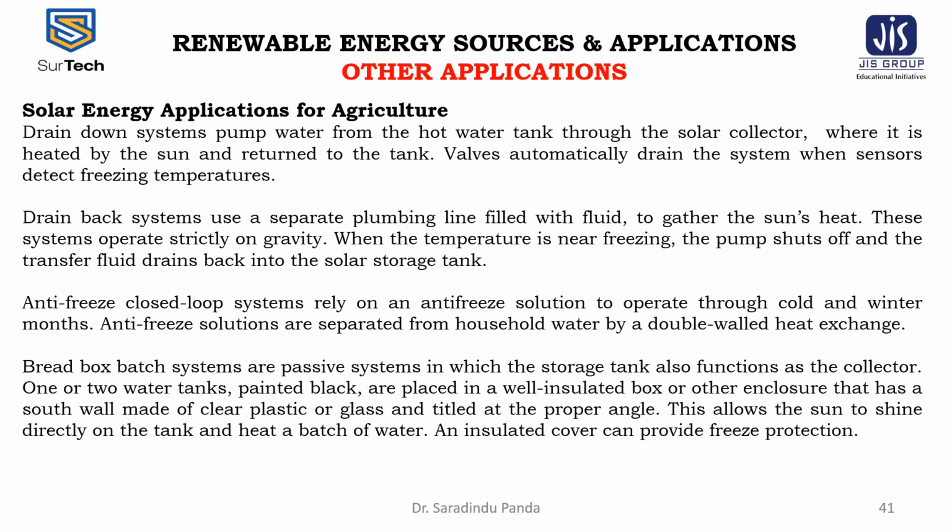Breadbox batch systems are passive systems in which the storage tank also functions as the collector. 1 or 2 water tanks painted black are placed in a well insulated box or other enclosure that has a south wall made of clear plastic or glass and tilted at the proper angle. This allows the sun to shine directly on the tank and heat a batch of water.